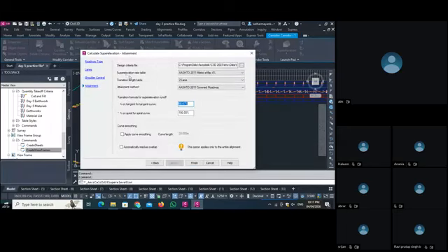So here you select the code with the help of which you want to calculate the super elevation. As we have a 2-lane road, I select the 2-lane. If you want to set your own design criteria file, you can set it from here. See what method it uses to calculate the super elevation.